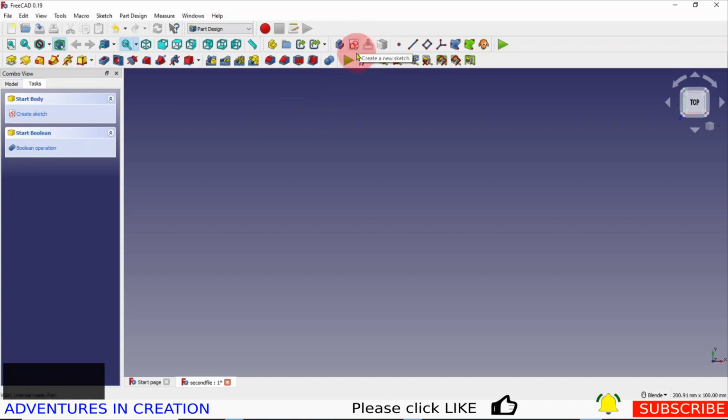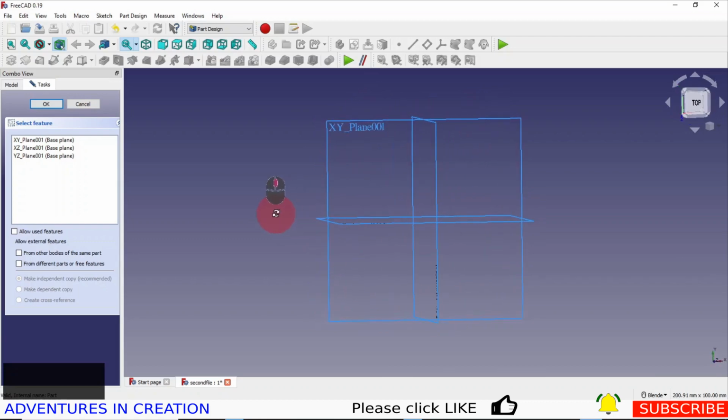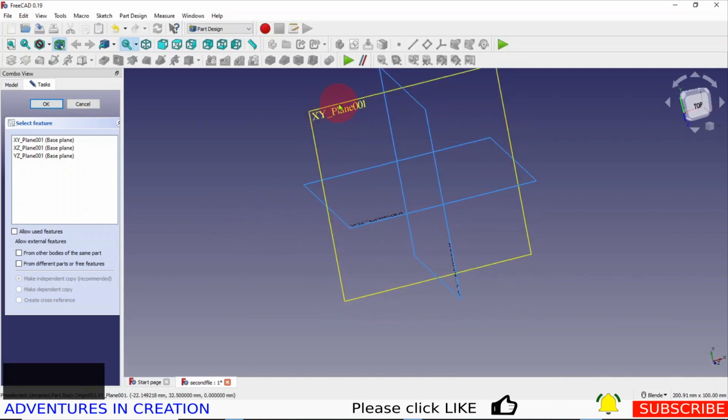Now, one thing to note is when you create a sketch, FreeCAD will automatically switch this Part Design to the Sketcher workbench. So let me show you that. Here's a sketch. I'm going to pick it on the XY plane. Now you've got two options here. If I just rotate this around, all I'm doing is pressing my middle mouse. That lets me rotate it around a little bit like that. I can select the XY plane from here. So if I select that plane, you see it selected it over there.